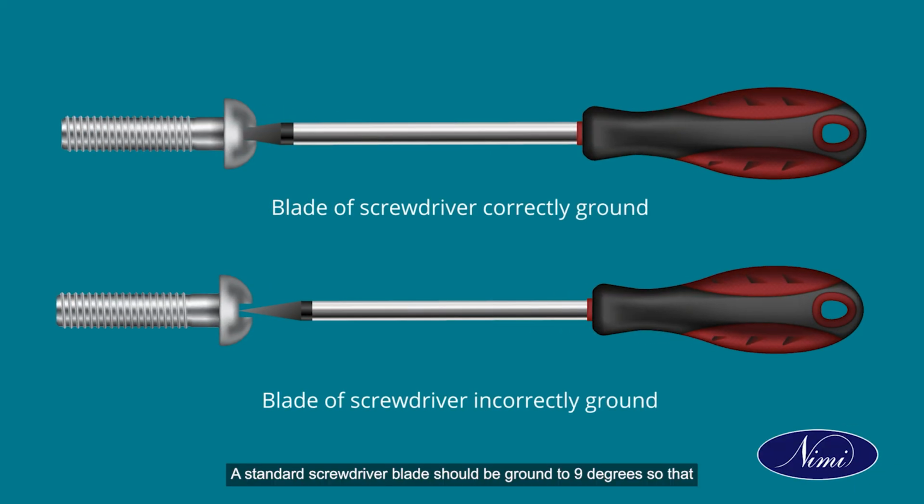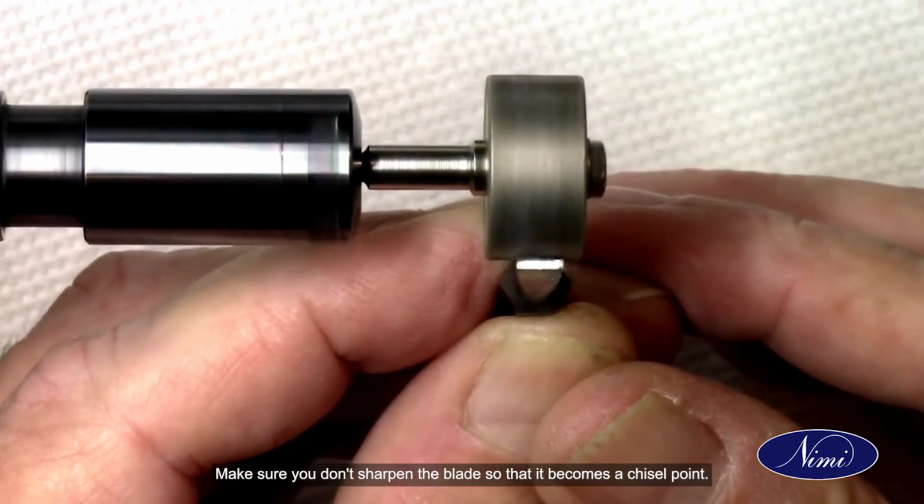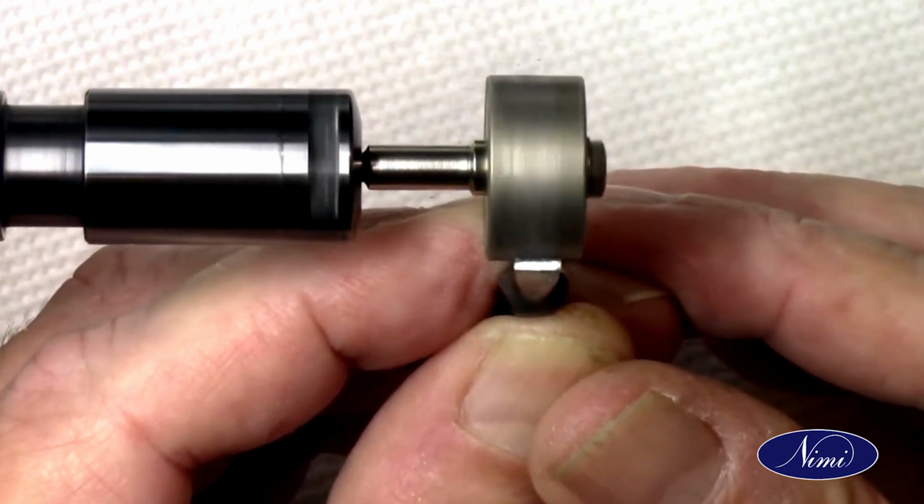A standard screwdriver blade should be ground to 9 degrees so that the face will be almost parallel with the sides of the screw slot. The end of the blade should be made as thick as the slot in the screw will permit. Make sure you don't sharpen the blade so that it becomes a chisel point.